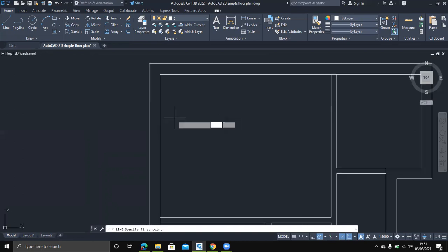And from this point right here, the first door has been drawn at an extension of 200, and that will be the door, the space that we will use. This will be the space that we will trim so that we achieve that space for the door. I will do the same for this other end here using the command PL, an extension of 200. I will be able to draw that as well.